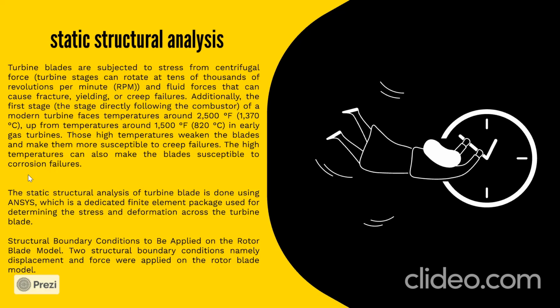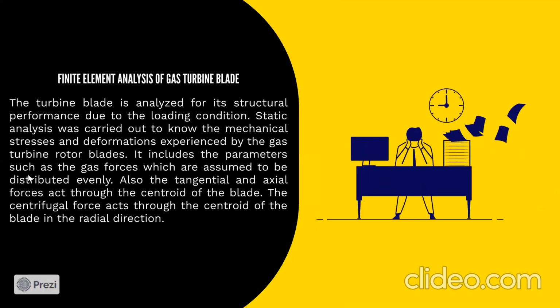The static structural analysis of turbine blades is done using ANSYS, which is a finite element package used for determining the stresses and deformation across the turbine blades. Structural boundary conditions to be applied on the rotor blades: 2 structural boundary conditions, namely displacement and force, were applied on the rotor blade model. Finite element analysis of a gas turbine blade. The turbine blade is analyzed for structural performance due to the loading condition.